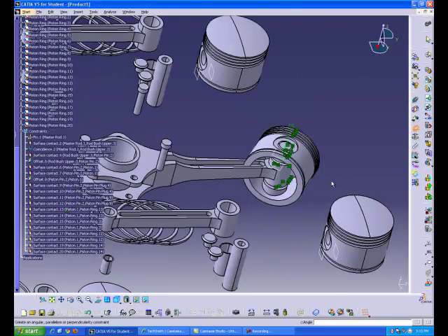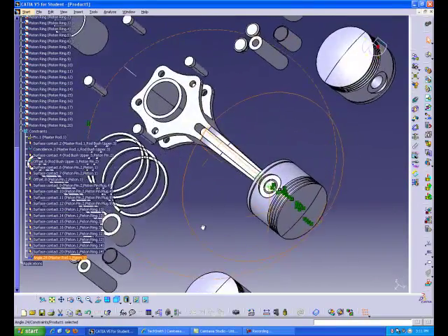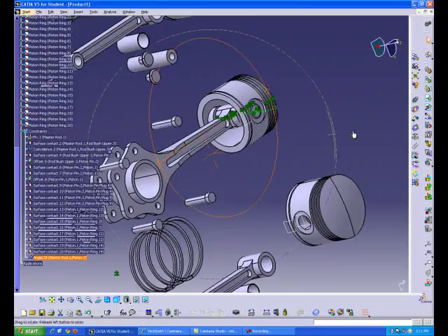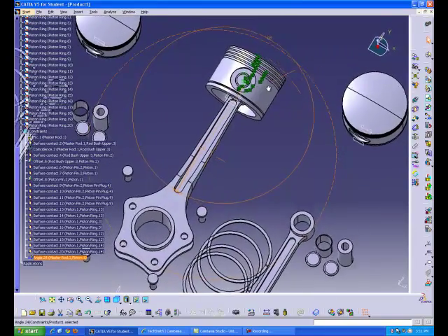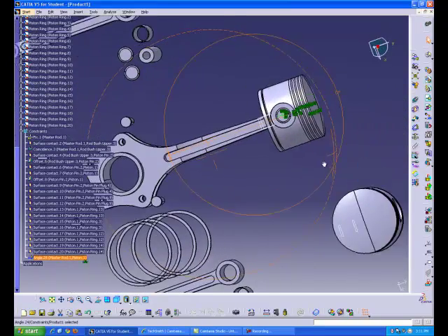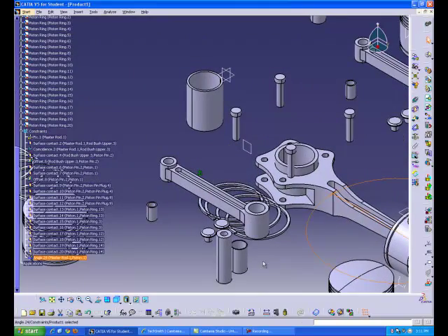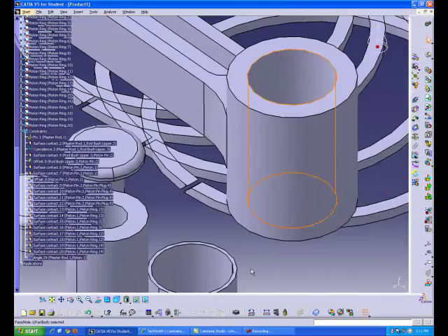To make the angle constraint, select the axis that lies along the master rod and the axis that lies in the piston, and make sure it's in the XY plane. Type in 0 degrees so they line up, and select update, and now it's fully constrained. Attaching the piston is the same when it goes onto the articulated rods as well.